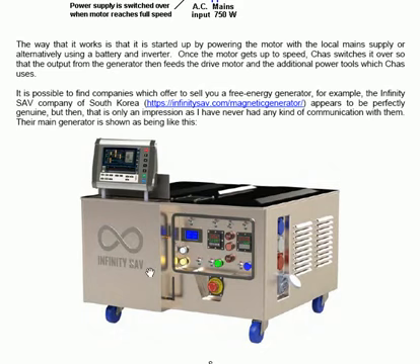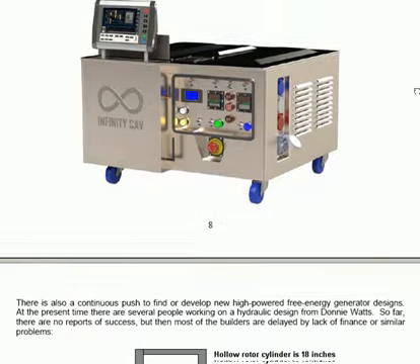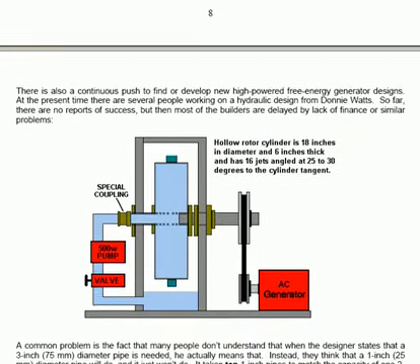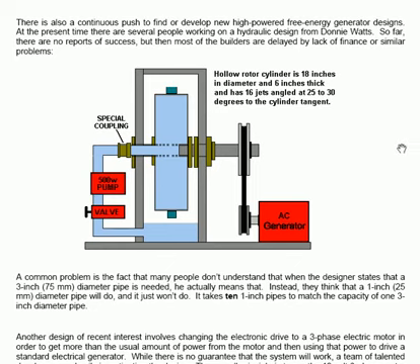The system is quite straightforward. There's a sump which contains a liquid, could be water. More generally, it's considered to use transmission fuel. A valve is opened and a 500 watt pump operates on a 3-inch diameter pipe, driving water into a drum which is set on bearings.